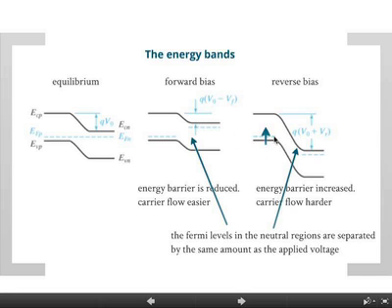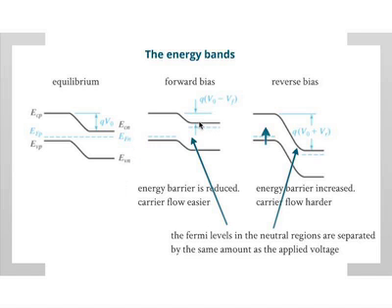So when you have reverse bias, it splits that way. If it's forward bias, it splits up. Okay? And we will see why that's important in a few minutes. But recall that the Fermi level determines the location where you have 50% probability of that energy level being occupied. Right? So if the Fermi level moves, that suggests that the carrier concentrations have changed.